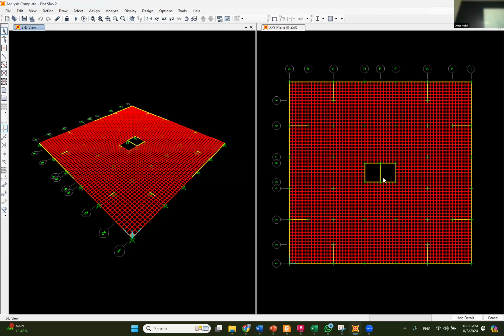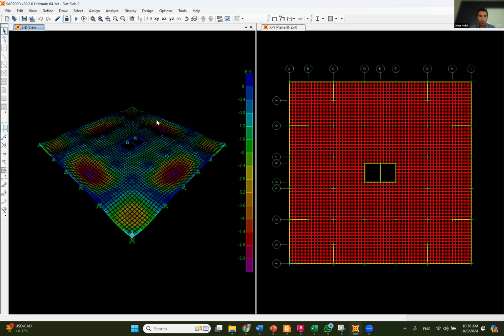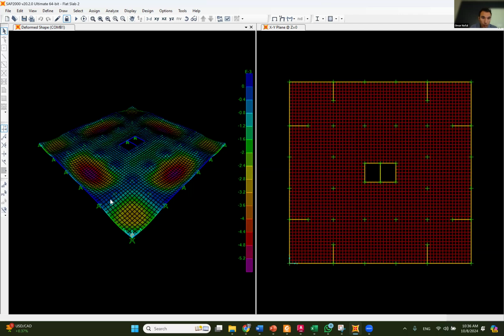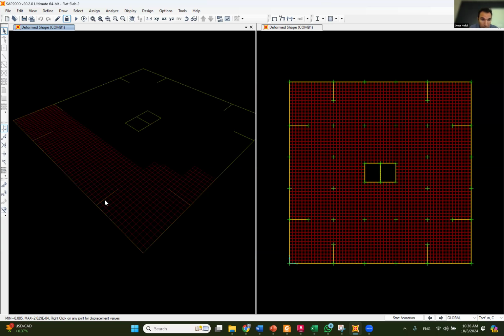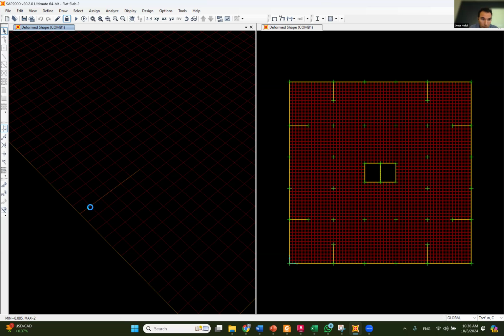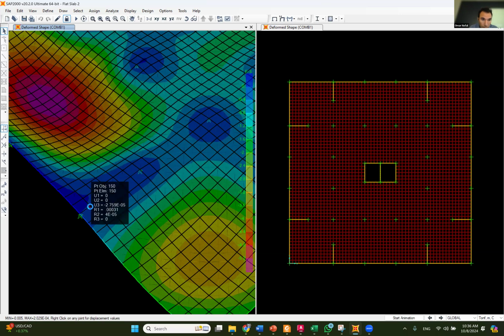All right. Okay, so let's check how much is the deflection now. The deflection, U3, it got less, like it's 0.00. Let me zoom in. Like here, oh, it's like -0.5. Like it becomes way less. The more that you increase, the right answer is 0. Okay, but we are close to it. Okay, I'm gonna accept that.